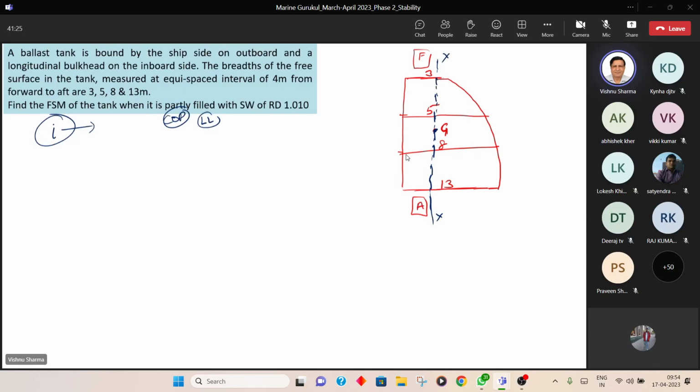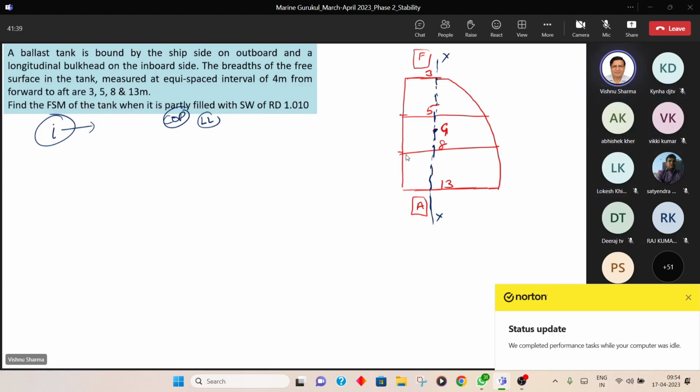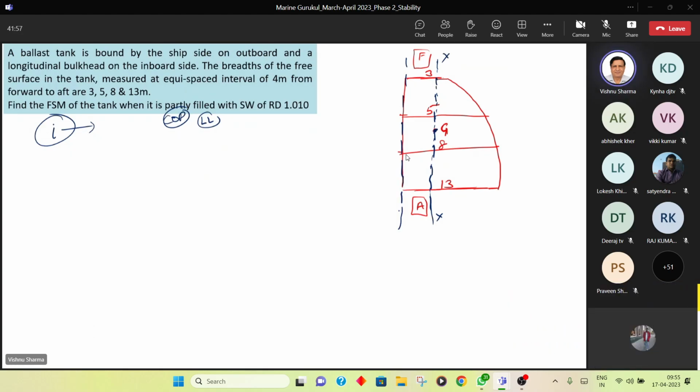Now, is it a case of horizontal ordinates with XX or vertical ordinates? Vertical, sir. Vertical ordinate, okay. And for vertical ordinates, we must have them terminating at one axis. So that means they don't all terminate at XX. Therefore, we will have to work about this axis first. This is because we have to work around out of compulsion, not out of choice. Had I been able to work about XX directly, I would have been happy. So I'll have to work about ZZ or YY, whatever I call first, and then get about XX. Am I right, guys? Have you understood why it's being done so?